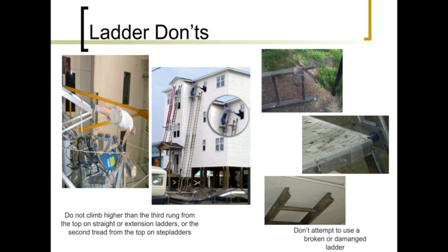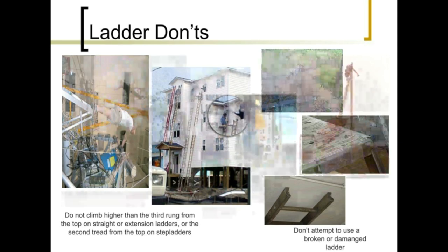Here's some pictures of ladder don'ts. Do not climb higher than the 3rd rung from the top on straight or extension ladders, or the 2nd tread from the top on step ladders. Most of them are marked, not a step. Don't attempt to use a broken or damaged ladder either.